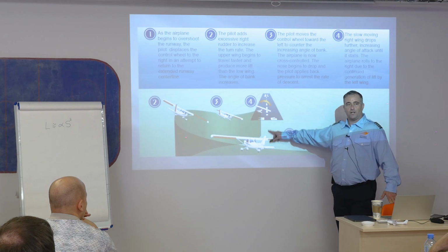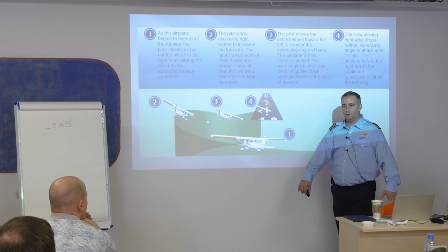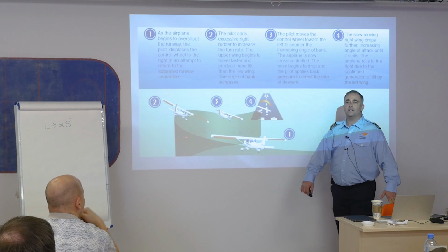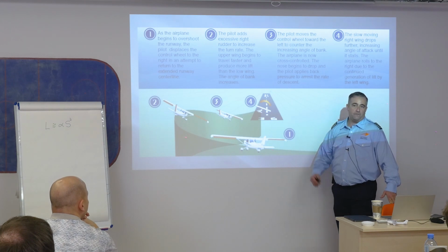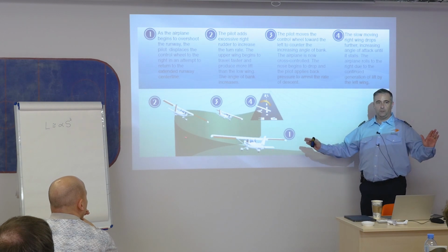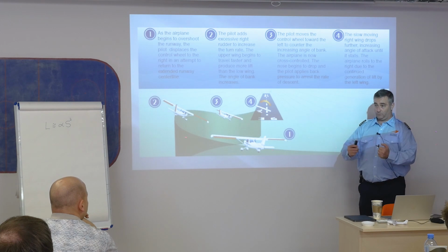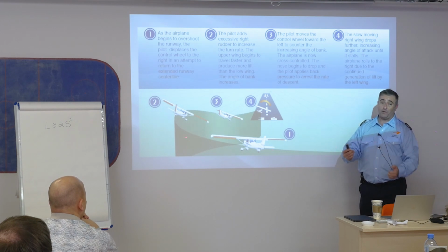All right? We're kind of close to the ground, so what does this sound like for me? What do I need to do? Do I just decrease my pitch? No, I think... apply some power as well. Yeah, full throttle, get the airplane flying, neutralize the controls. If I have rudder and aileron, just make them neutral. Okay? And the airplane will fly again.